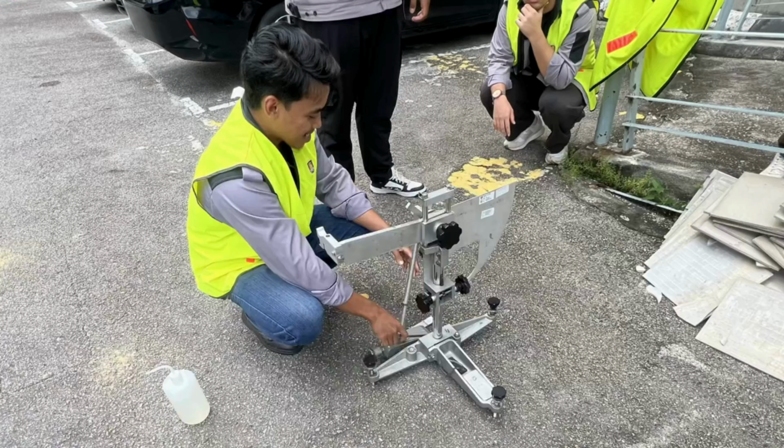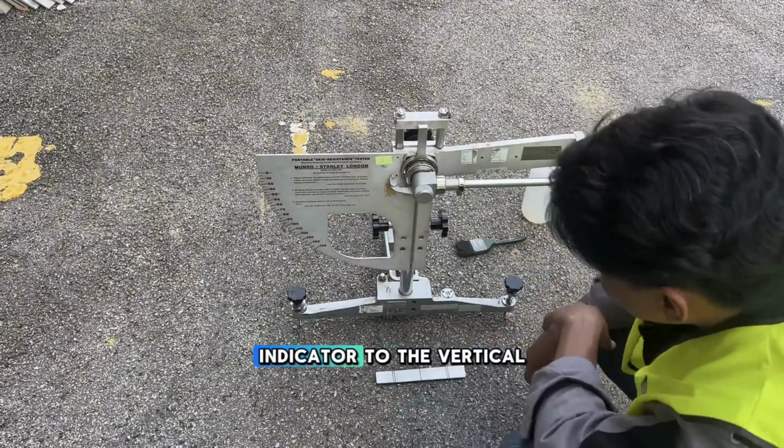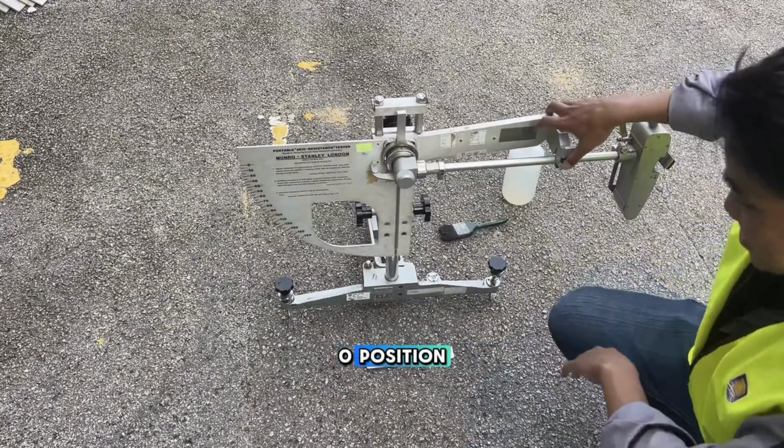Firstly, clean the test surface to remove dirt and loose particles. Second, level the skid resistance tester by adjusting the base until the bubble is centered in the circular level indicator. Next, loosen the locking knob so that the pendulum arm can swing freely. Adjust the tester height so that the slider rubber just touches the surface at 3 reference points. Set the maximum swing indicator to the vertical 0 position.